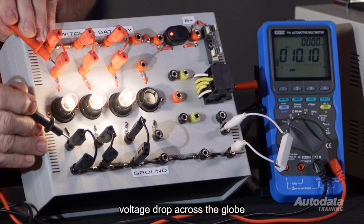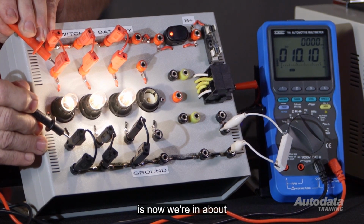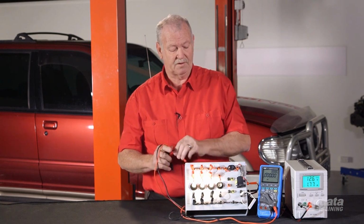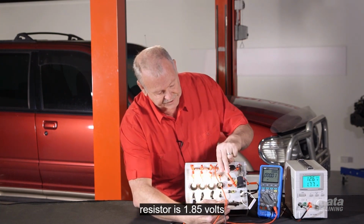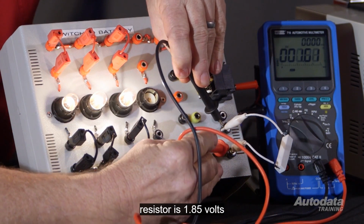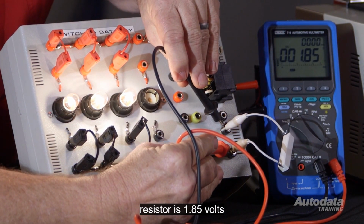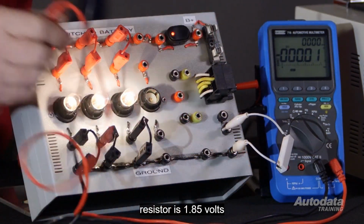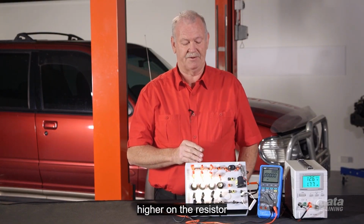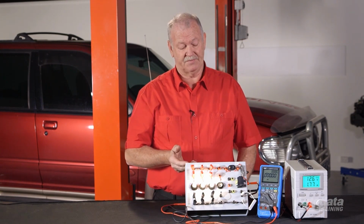The voltage drop across the globe is now around about 10.1 volts. It's lower than it was before. The voltage drop across the resistor is 1.85 volts. The voltage drop is now higher on the resistor. Why is this the case?